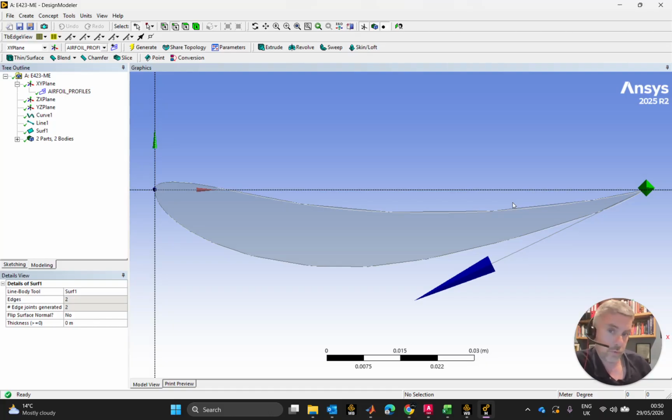I have big downforce on the low to medium speed. It means I have an absolutely phenomenally large, massive downforce on the straights, which isn't good, but that has to be dealt with in another way. I mean, bring in some active air or DRS if you want. But the thing about it is I am going to be looking to achieve a certain amount of negative lift at a low speed. So I'll need a fairly substantial airfoil to do that in principle.